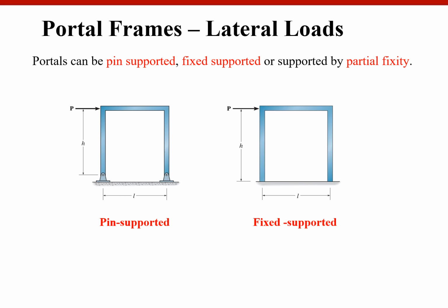Okay, we now have portal frames. When you have a frame without bracing, we call it a portal frame, so that it can be used as an entrance for a huge truck or something. These days, the internet industry uses the term portal as an entrance. Anyway, when you have a portal frame, we have pin supported or fixed ends. Of course, when you have pin supports, we are going to have two unknown reactions at each support location.